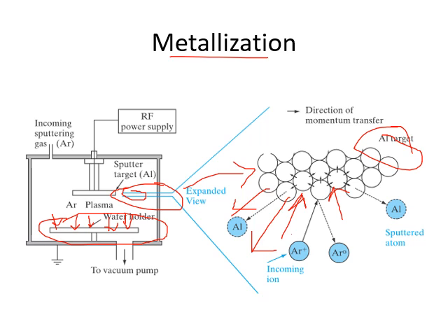But we again go with photolithography to remove the unwanted part. Everywhere there will be aluminum, but we don't want the aluminum to be present everywhere. So we etch away the aluminum wherever it is not required, again using a photoresist mask and UV radiations. So these were the topics we had covered in the previous lecture.